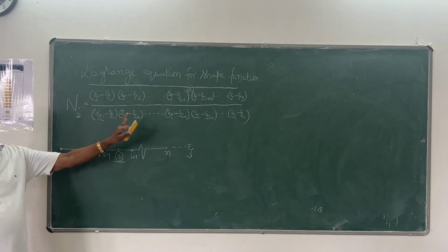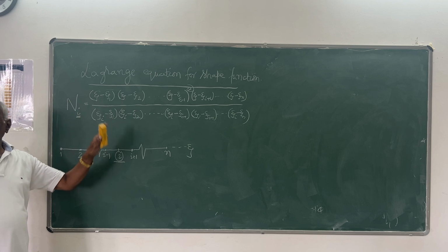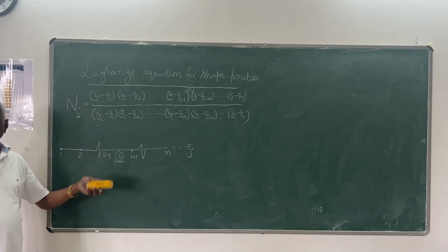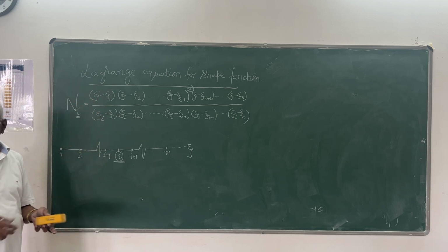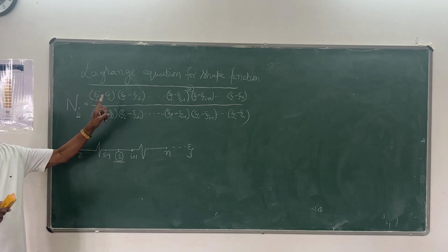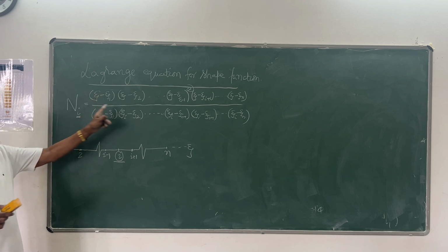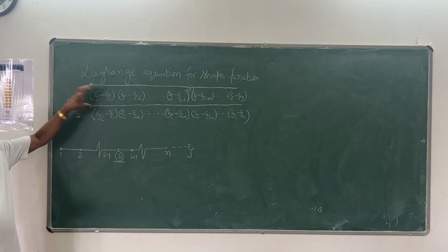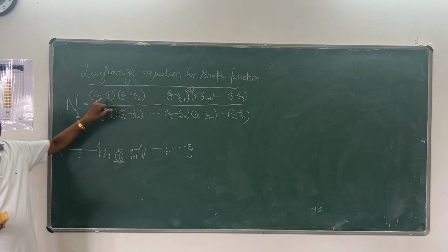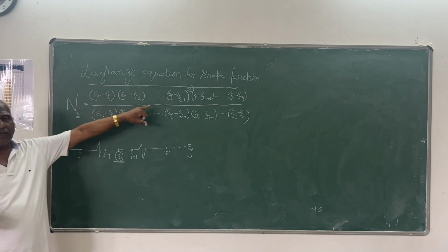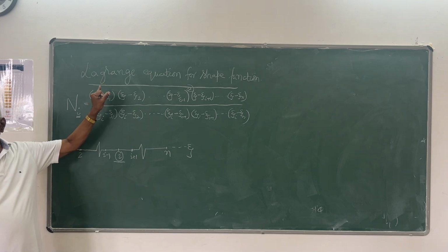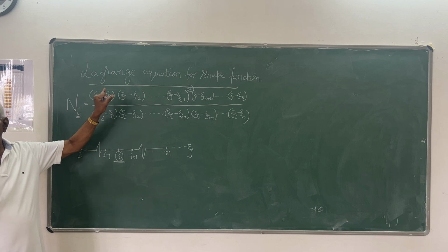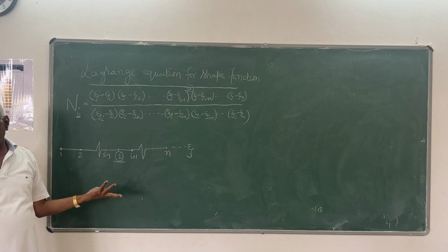This is the simple formula. You need not bother about inversion and all those things, as you have the general procedure for finding the shape function using Lagrange form. One is this formula, you do remember, wherein the numerator consists of only the general variable, either psi or x, depending upon whether you are applying the shape function in global form or in natural coordinate form.